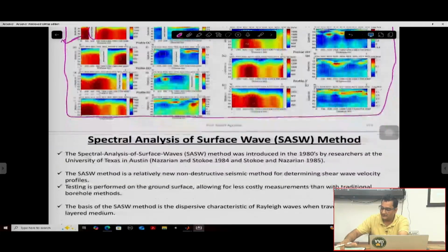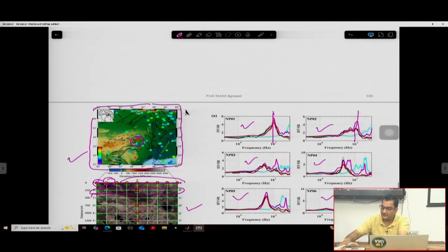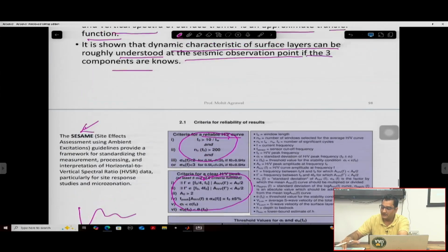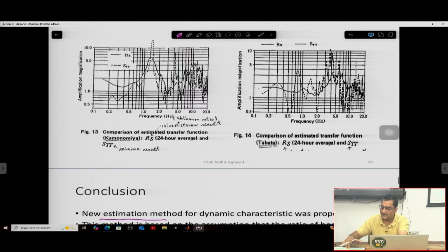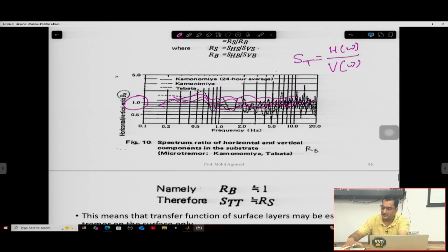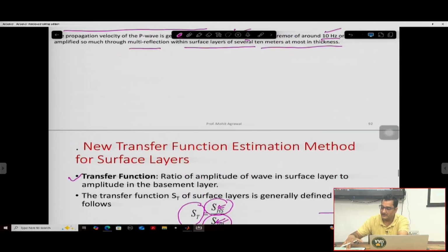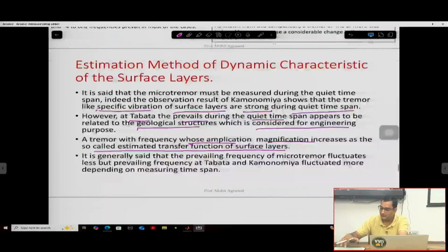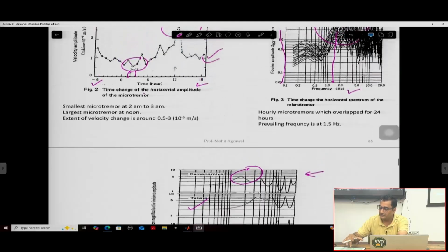Thereafter, HVSR. So far, what did we learn about the HVSR curve? HVSR is a cost-effective technique that can be computed using a 3-component seismogram. We divide the entire continuous recording into a number of windows, and for each window we do a fast Fourier transform. Thereafter, we take the mean of the horizontal components and divide it by the vertical component. This technique is very important for finding the fundamental resonance frequency